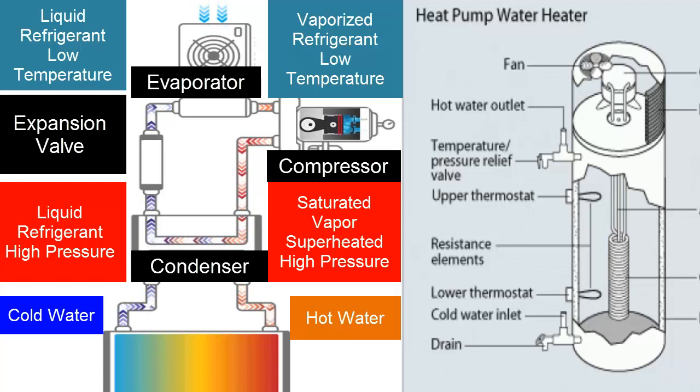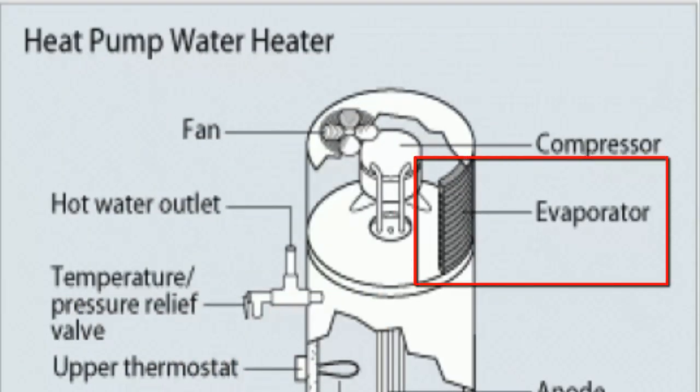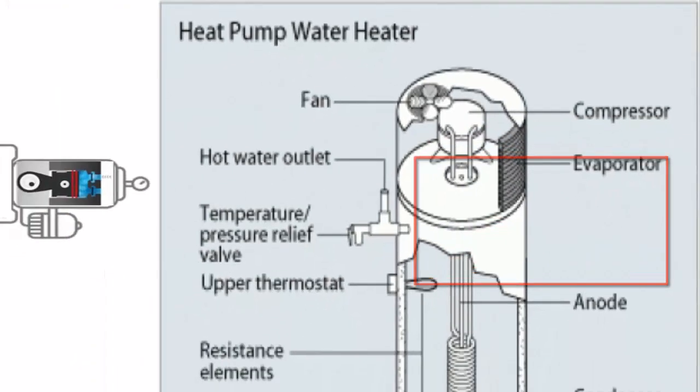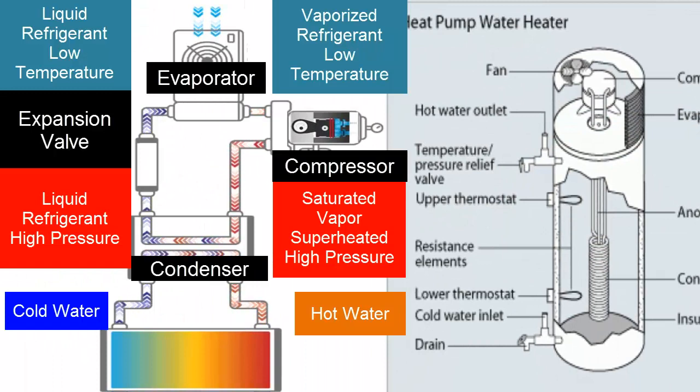D. Evaporator is another heat exchanger, located at the outlet of the expansion valve, which, through its surface expanded by a fin system, and by having reduced its evaporation temperature below the external air temperature, allows the exchange between the refrigerant fluid and the external air. In this heat exchanger, the refrigerant fluid changes from liquid to a saturated vapor state.